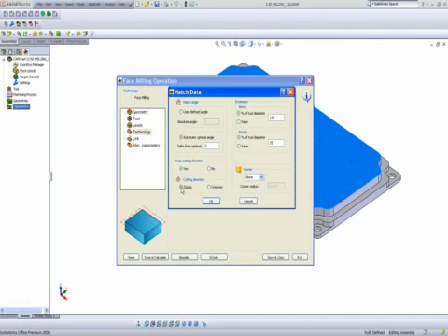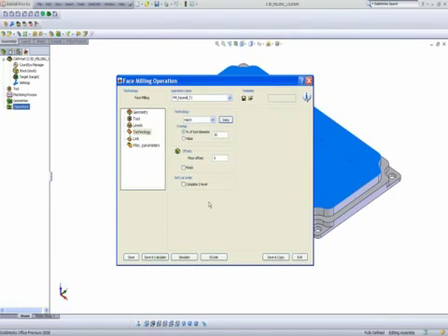Now I can go either zigzag, back and forth, or in one direction. We'll choose the option of zigzag, and my corners, I can have them fillet also. This is particularly good, especially when you're working with higher feeds. I'll say OK.